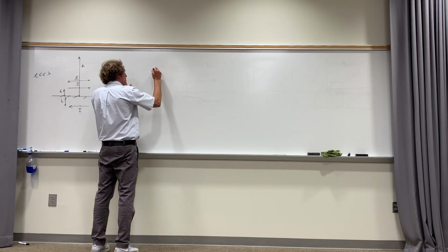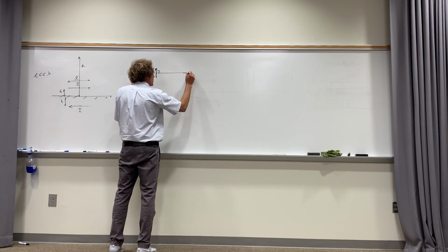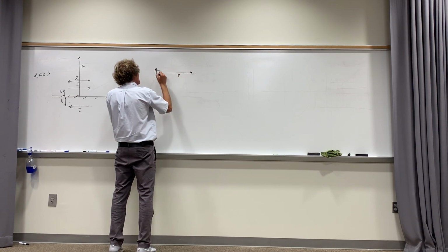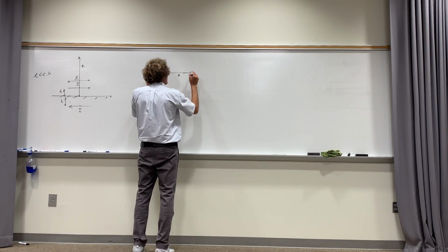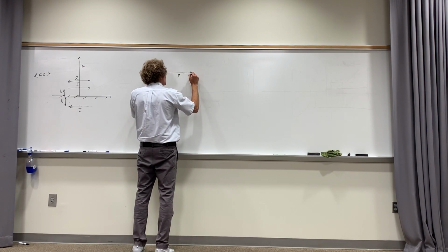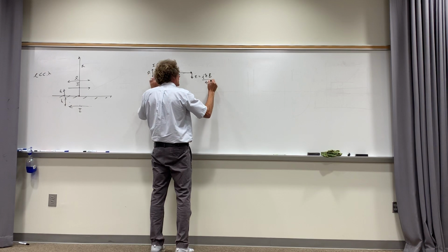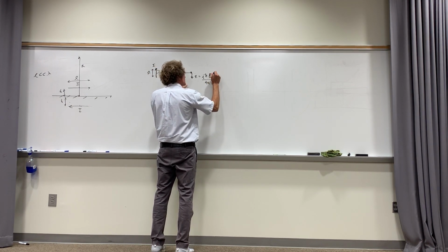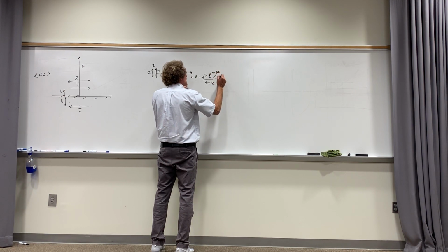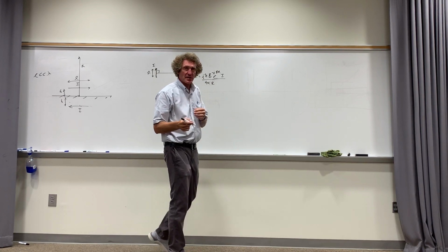If I have a short dipole like this, and I come out perpendicular to it at a distance r away, and this has a current I, it has a length L, then I know my electric field here would be equal to j eta beta over 4 pi divided by r times e to the minus j beta r, and it would be times I, and then it would be times sine of theta, but since theta is 90 degrees, it's 1, correct?